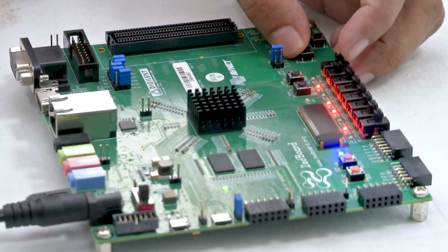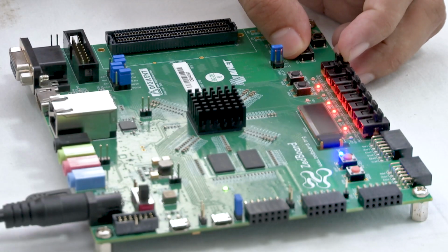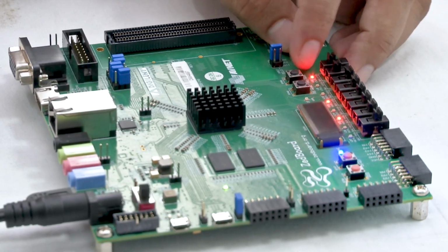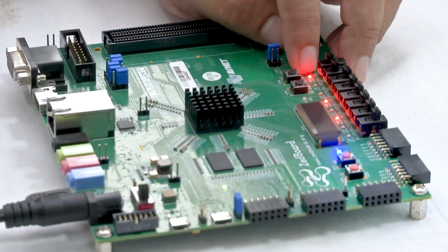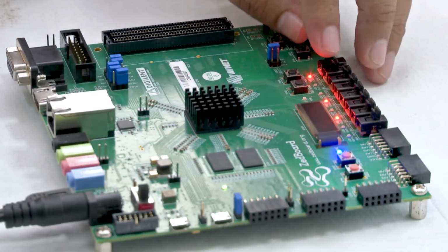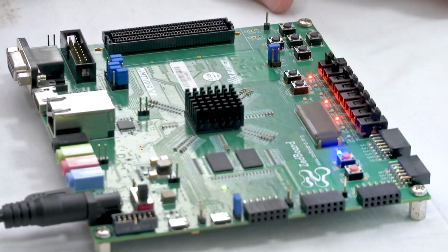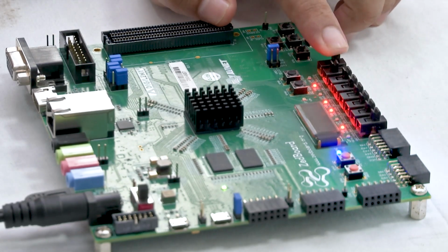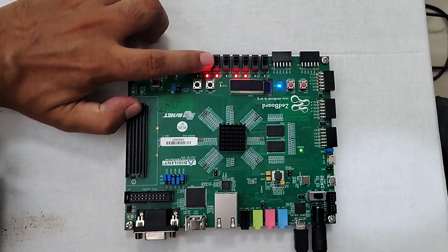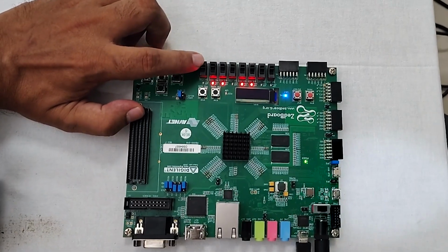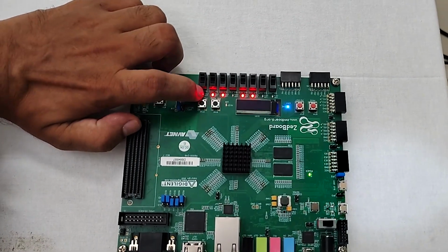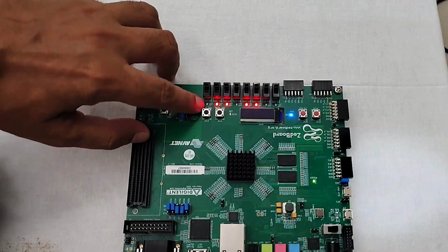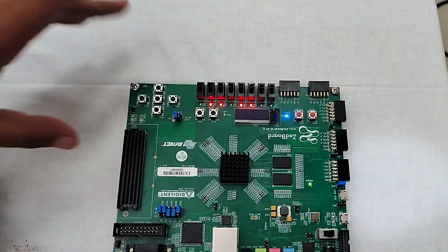Now again for 0, 1, same, you can check the OR gate, AND gate, NOR gate, everything. For 1, 1, you can check that the AND gate will blink. It will be on, but XOR will be off, since the inputs are 1, 1, so the XOR output will be 0. You can verify all the gates by switching the sliding switches, giving A and B as input, and the output can be seen from these LEDs. Like this is for the AND gate, this is for the NAND gate, this is for the XOR gate.